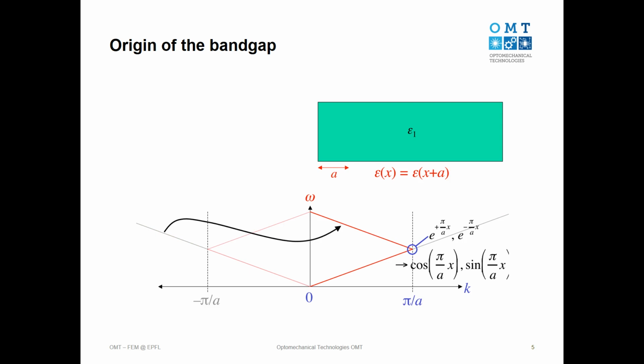treat my medium as a periodic medium? If I move by A, it's still epsilon 1, right? So I have originally this dispersion diagram, and I will have to shift it by 2 pi over L. So it gets shifted if I consider this to be my permittivity. Here I will have another curve shifted here. So my structure gets sort of folded. This is from my initial dispersion diagram. This is from the one that is 2 pi shifted. Continue with this one, you find something here, and it goes on and on, so you get a folded structure going on.